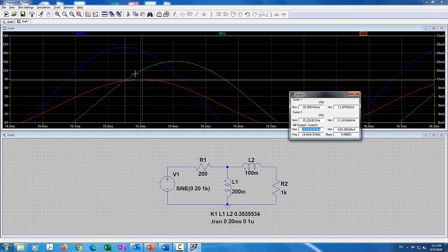However, I like students to also use this technique, because when you use an oscilloscope in the lab, that's how we're going to measure the phase. Basically, we ask what's the time from the reference peak, which is the Vn, to the current peak, and then you multiply that by frequency, and then you multiply that by 360 degrees, and that's going to give you the phase difference.